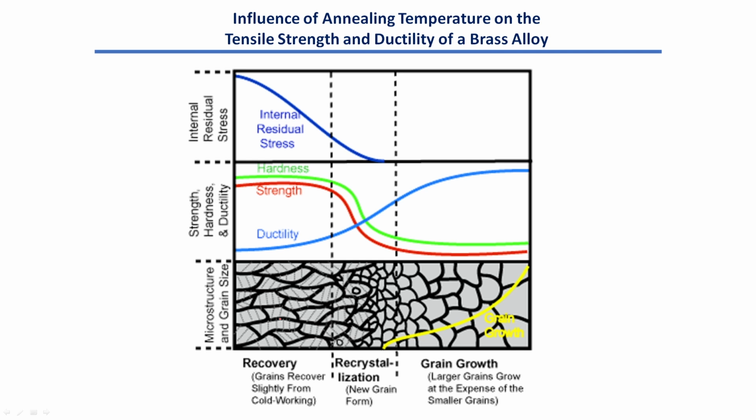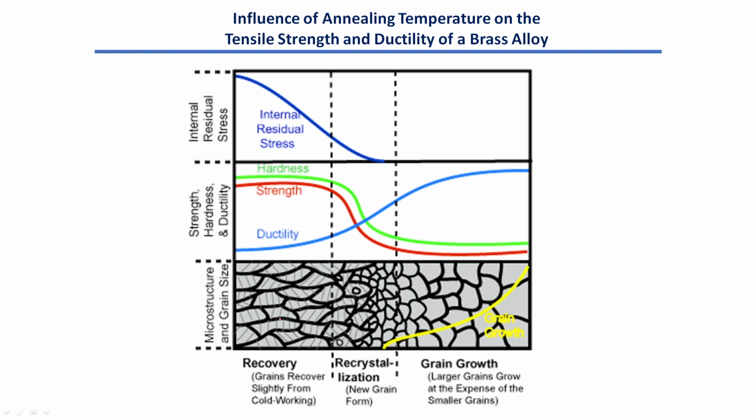Remember, if I generate a lot of dislocations simply by hammering a piece of metal, because the metal is getting hammered, it has to plastically deform. The only way of plastically deforming is by generating a lot of defects, and they will be generated randomly. So they will not have time to align properly so that they can reduce the energy. Once you heat it up, the first thing that happens is that they can align properly and reduce the energy, and in the process what will happen?